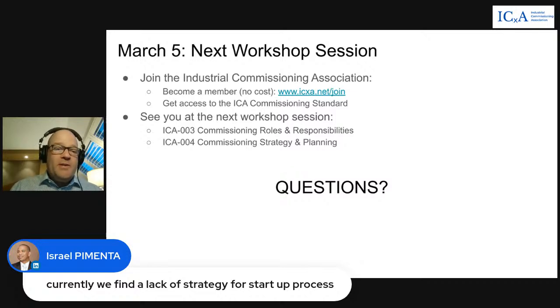You need to know how you're going to start up your project before you go design and build it. If you go design and build your project, but none of that aligns with your startup sequence, then you're guaranteed delays, very expensive delays. You've maybe heard the term, you need to plan projects from right to left, right? Pick your in-service date, and then the first thing to define is your startup sequence.